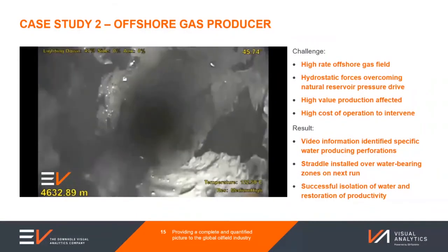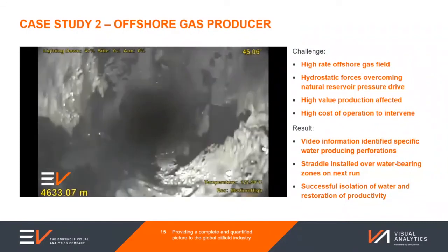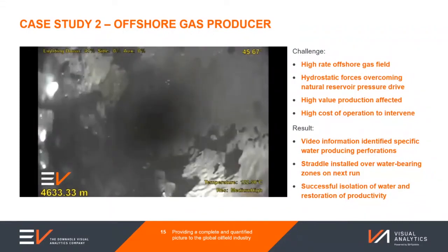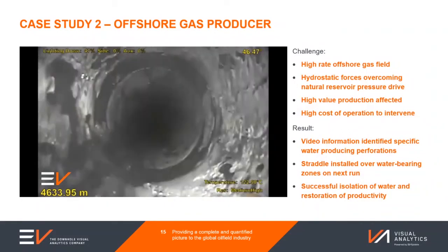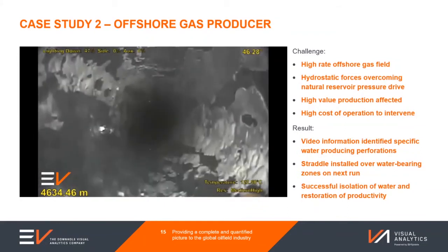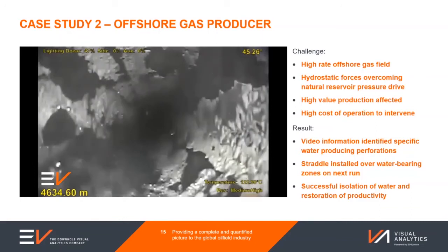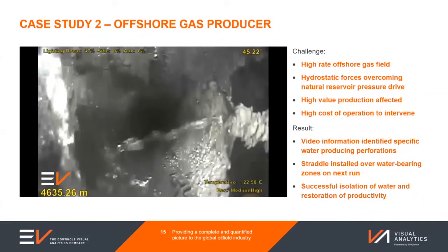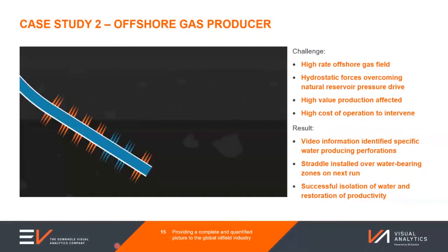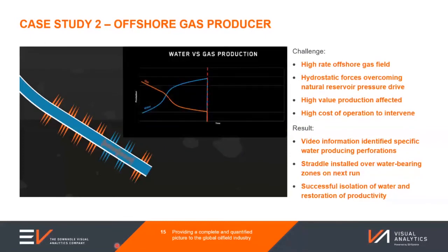The production log showed areas of interest, and there were some points where you could clearly see elements of water, but it was only really when you looked at the video that you could again see the individual perforations and their exact location to find where the water was coming in for sure. The additional bonus of seeing the video is it identified quite a large presence of scale in the well. So before the solution could be placed into the well, the operator, who was planning to run a patch, a straddle, or a plug, depending on the results, was able to see this scale and perform a cleanup operation to help the seal assemblies provide maximum effect when they were set.